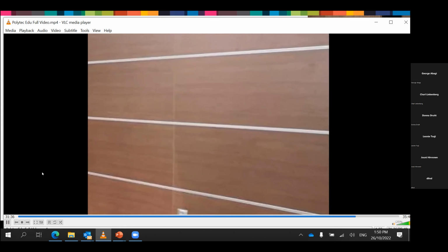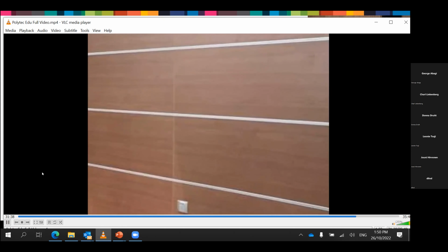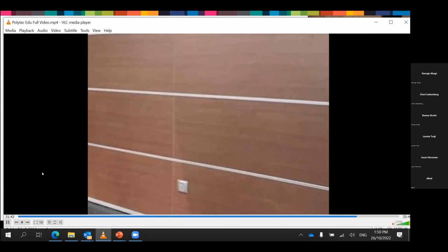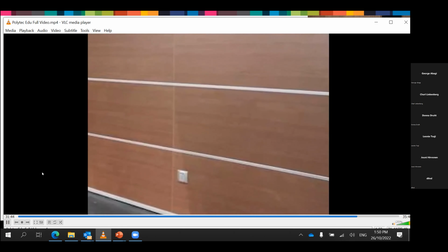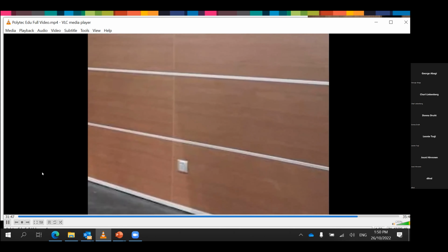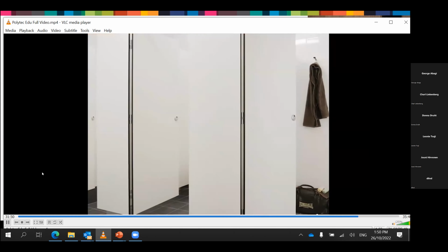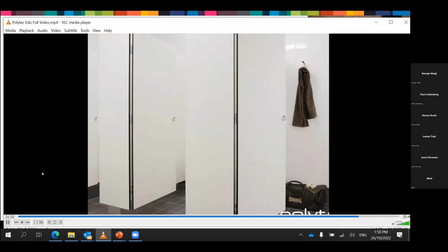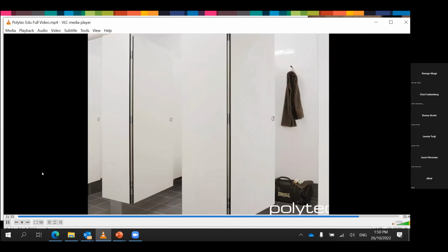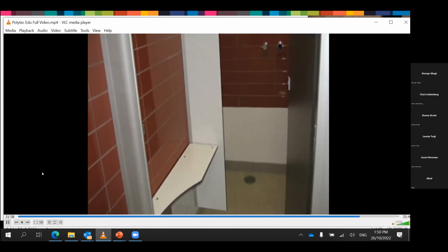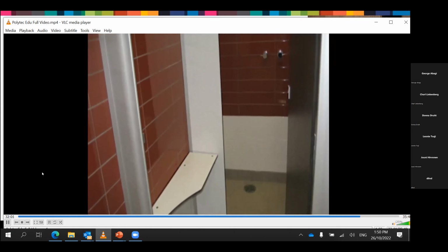Sheet size constraints. Optimal sheet size is 3,660 by 1,830mm wide. Anything less than 1,600mm in width would require a joint inner panel. 13mm multi-purpose compact laminate is the preferred material to be used in toilet and shower cubicles within educational buildings. This is due to its strength and durability.